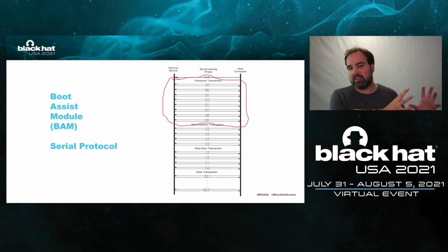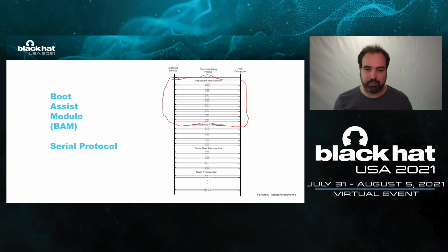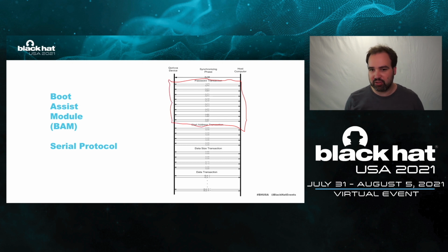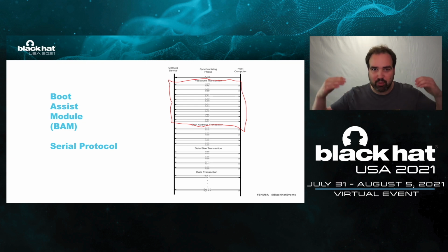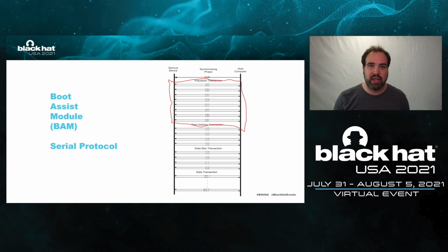So this is just like a first stage bootloader. You have to make your own second stage bootloader to actually do anything, right? All it does is run code from RAM for you, if it accepts the password. So what we'll need to do, the kind of point of this talk is mostly about this, is that password, how that comparison works and how you could bypass it. It turns out this is a nice attack because it's pretty low level. So no matter what people do at a higher level, no matter what the ECU manufacturers are doing, this ends up being sort of a problem for them because this gives you access to the core memory itself.